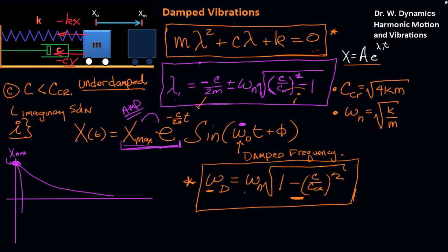And then our period will take longer, so our oscillatory motion will look something like this as it decays out. So that term defines that range of amplitudes decaying per cycle. And also note that our period will have gone up when compared to the undamped vibrational system.